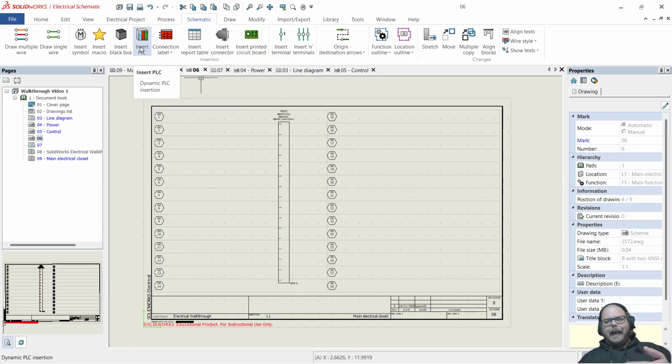The other part of that is they also have, and it's pretty powerful, a built-in sort of I/O labeler. So it'll actually automatically label the I/O points, label the wires to match that I/O that are going in. The problem is that it's a little outdated in that it is based on the old days when PLCs had direct memory addressing. So it's sort of meant for older PLCs, sort of like the MicroLogix, where an input point in the software would be labeled like I0:0/1, right? That's a direct memory address, and that's sort of the way SolidWorks Electrical addresses things.